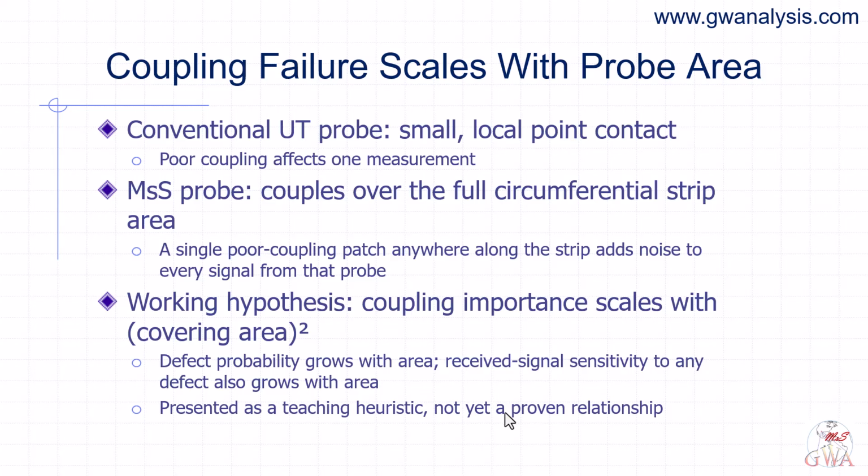In guided wave testing, unlike point contact UT, coupling is not a per-measurement concern. It is a continuous, cumulative one across the entire probe contact area. A single weak section of a strip contact degrades the entire data set, not just one reading.